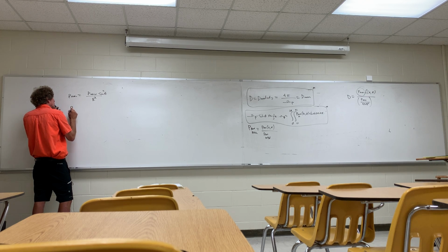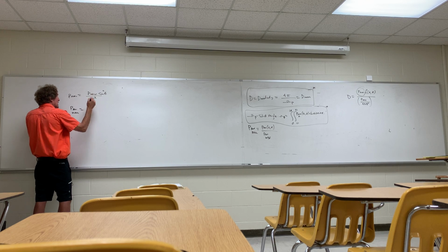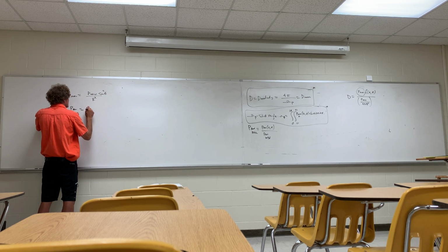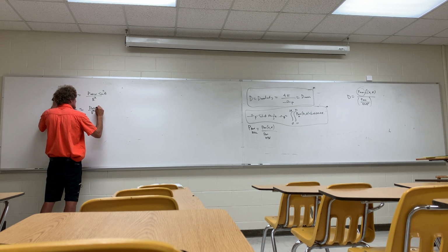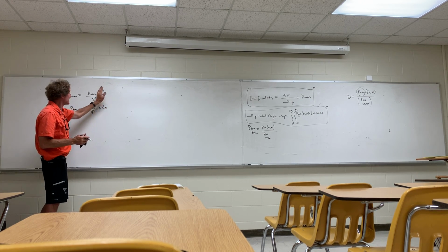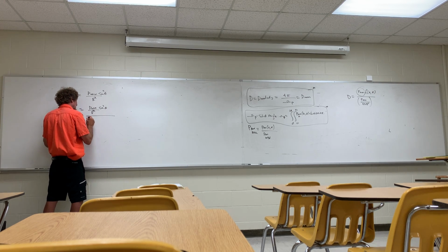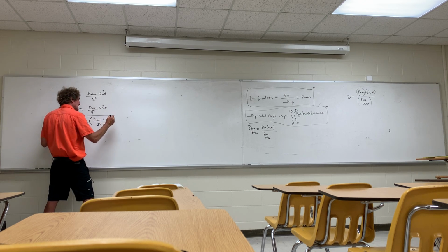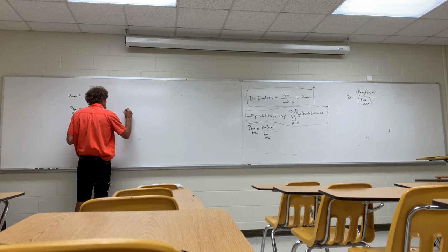So then, when I normalize the average power, I take this value, R squared, times sine squared, and I divide it by its maximum value. Well, its maximum value is that. So I'm dividing it by P max over R squared, and it's simply sine squared theta.